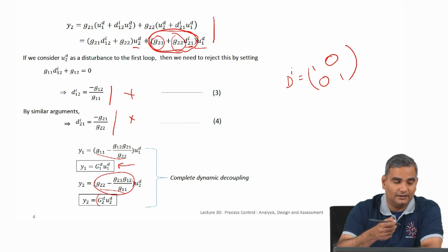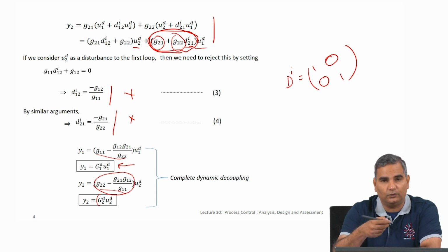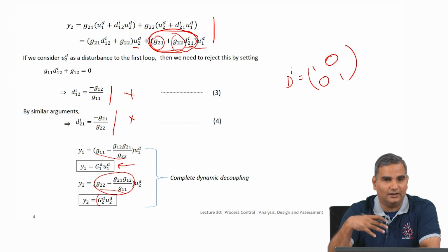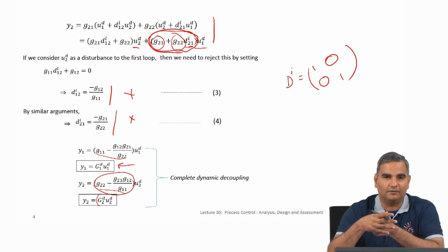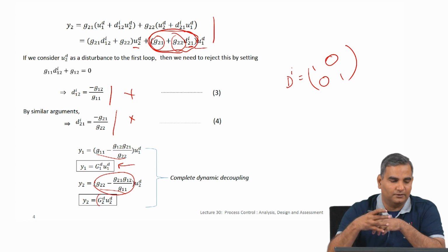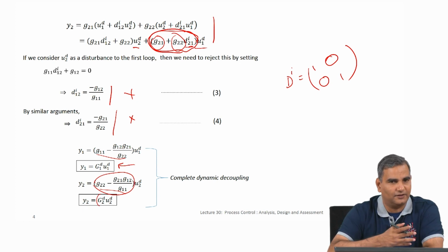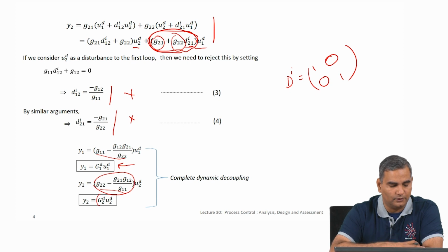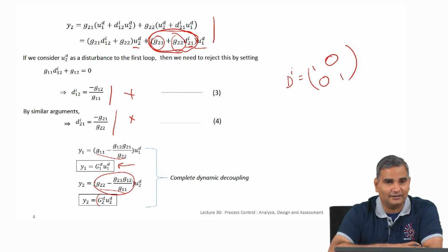And the way we get these transfer functions for y1 and y2 themselves are simple algebraic manipulations. And so, lots of other things that we are doing here in terms of decoupling and so on all get completely merged in some simple algebraic transformations which are very easy to understand. So, I hope you got a good idea of how you do this for 2 by 2. Now, if you have 3 by 3, it is the same idea, there is nothing particularly complicated there.